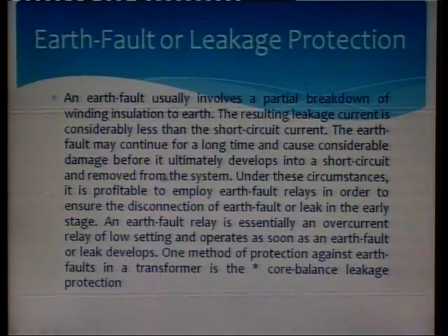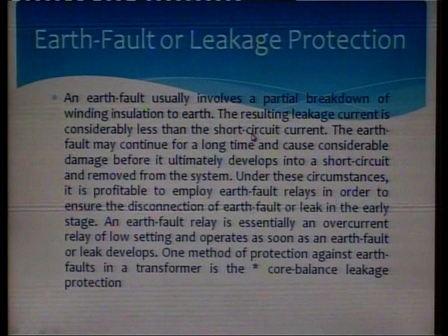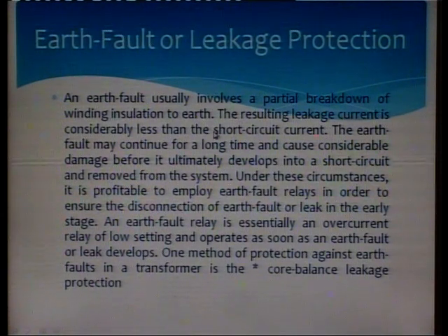So, the earth fault may continue for a long time and cause considerable damage before it ultimately develops into a short circuit. So, it says that although the earth fault's short circuit current is not very severe, if we let it continue for a long time then it will take a severe form.